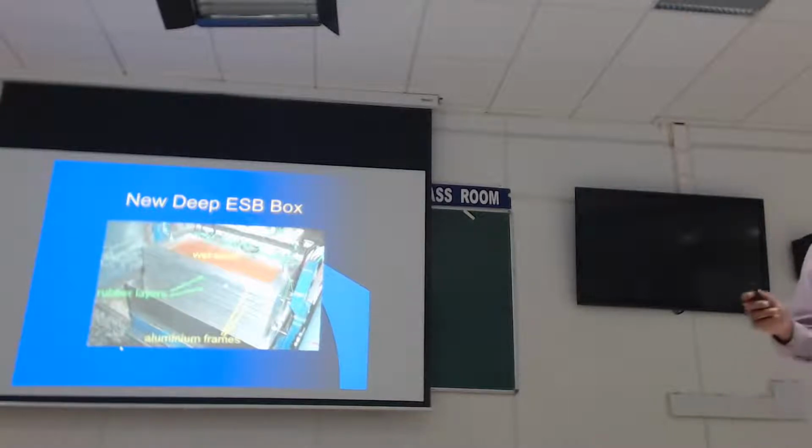The biggest box with soil you can put on that can only go up to about 6-7 meters of soil depth. So, just the structural frame, they can test up to 7 floors. But if you make a big box like this and fill it up with sand, the maximum sand before you reach the capacity of the shaking table is about 6 to 8 meters.